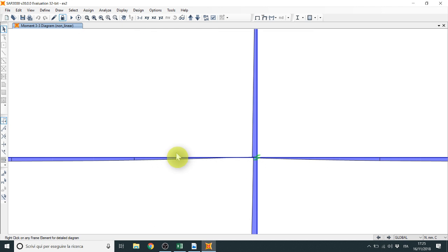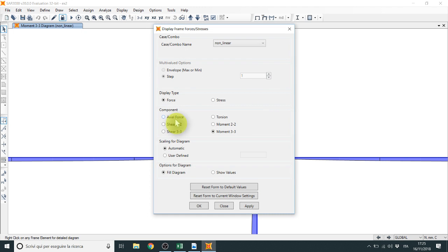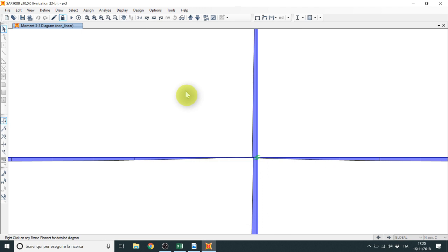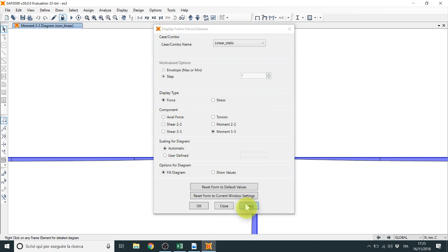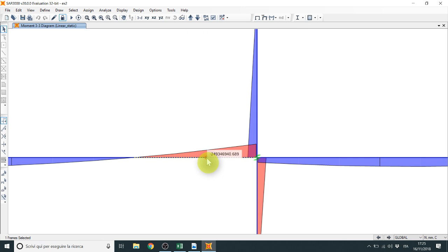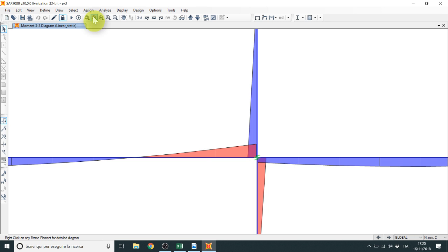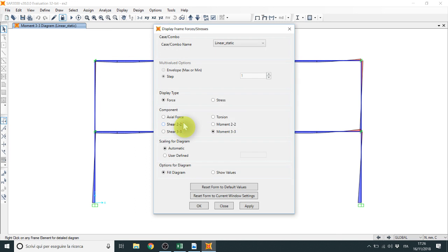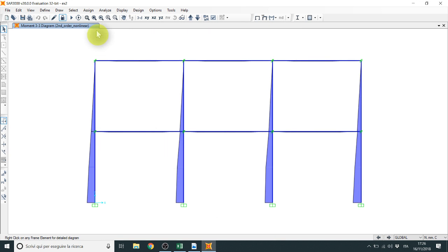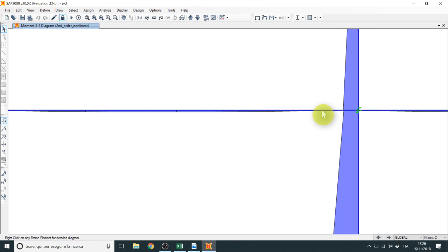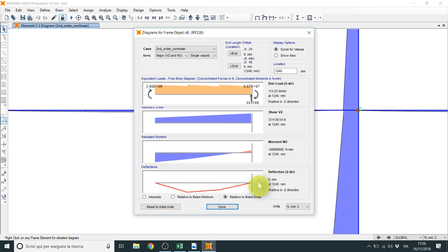If you perform a linear analysis with the link, you will not consider the link, but only the elastic part of the link definition. And the last thing, of course, the second order analysis with the P delta effect will depend on the link behavior. So you will have the limit of 60 on the joints.